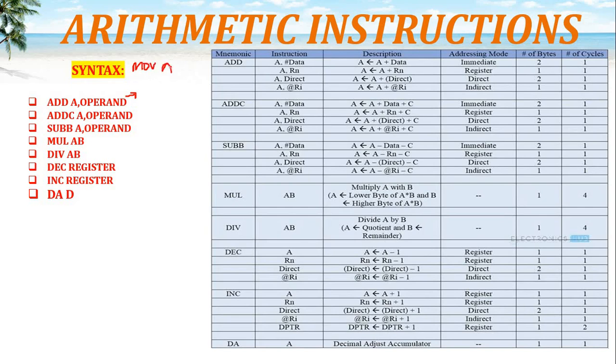That is MOV A comma #25. This is the first instruction. The next instruction I'm going to give is ADD A comma #50.